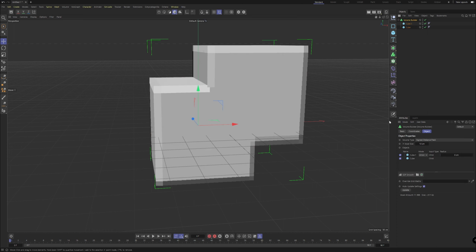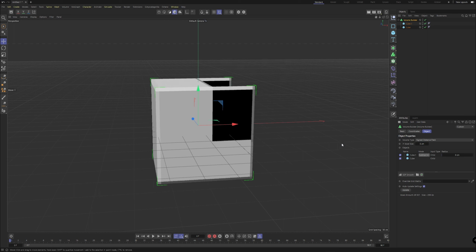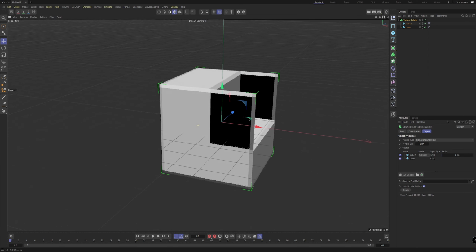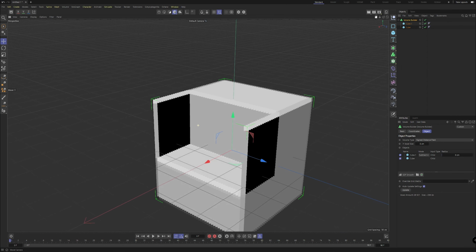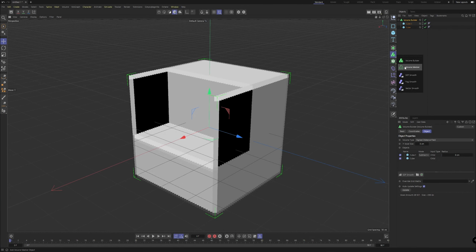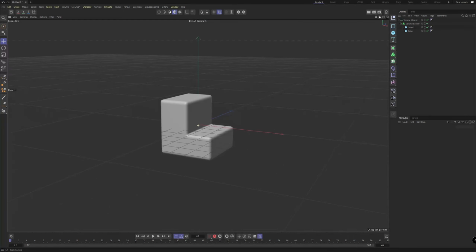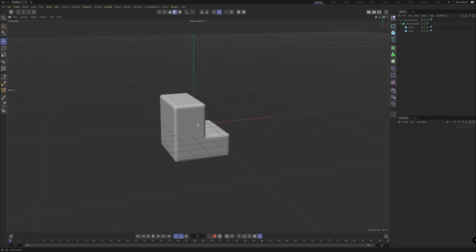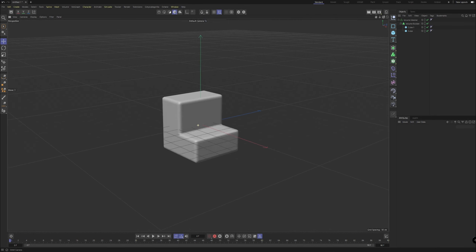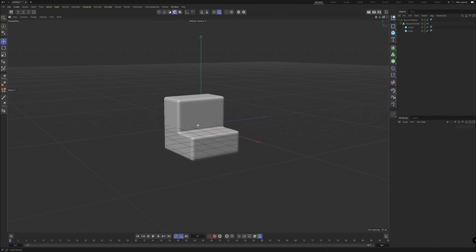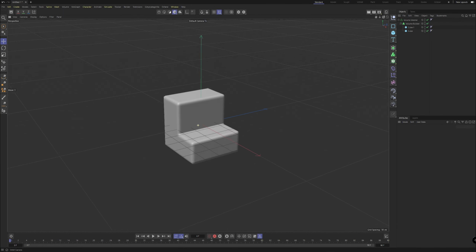If you put this in, it's going to convert it to voxels. The more you move the voxel size down, the more detailed the geometry is going to be. So if we move this down to 5 and set this to subtract, you're essentially ghosting that out of the other one. Although that seems a little counterintuitive, when you start meshing this eventually, you can smooth this out and combine a lot more shapes to genuinely create the ideas that are in your head. I don't know why, but for me this seems so much simpler. Obviously, later on you can fix the holes, and if the geometry needs fixing or a different modeling technique is required, you can do that.